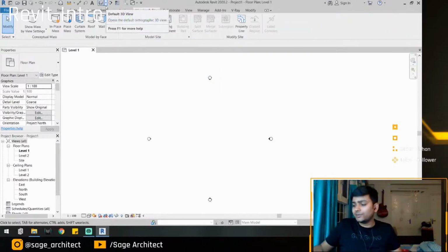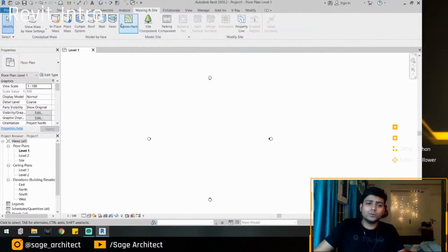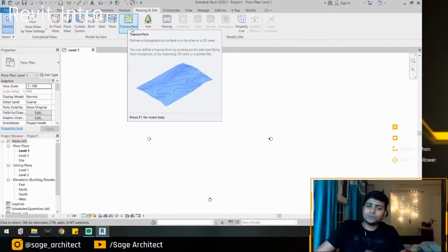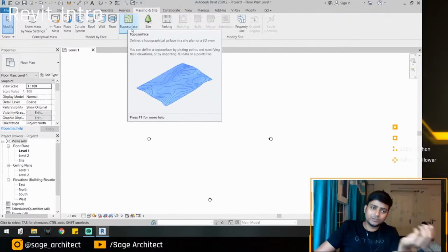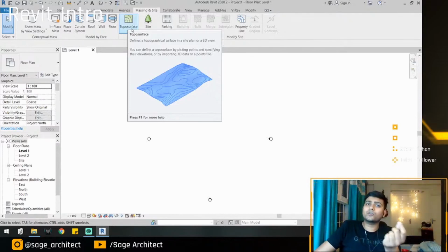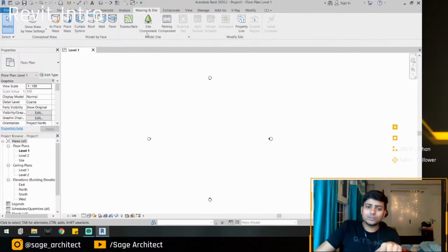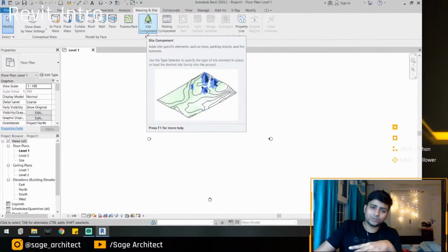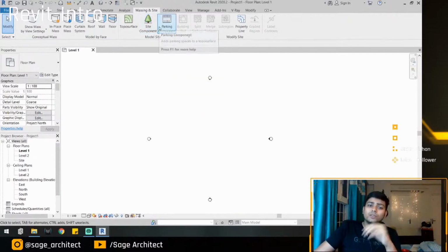The good thing about Revit is that if you want to make a topo surface, that is hilly area, hilly region, and all those kinds of things, it is very easy to do it in Revit. So there are options. You can get the survey data from the department, or you can acquire it from some place, and you can put the data in the software, and it will create the 3D surface itself. Or you can do it manually by creating all the contour lines. Generally, the figure you get after the contour, after the survey is done. So there are two ways of doing it.